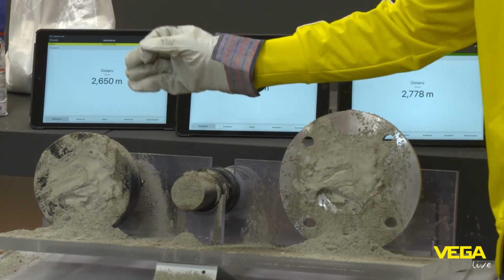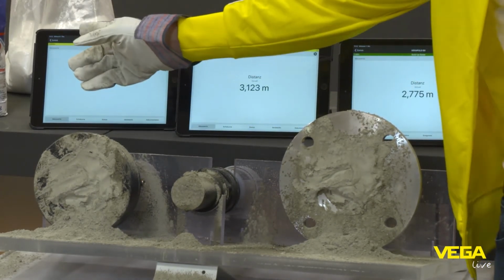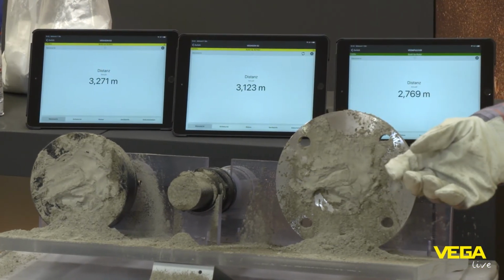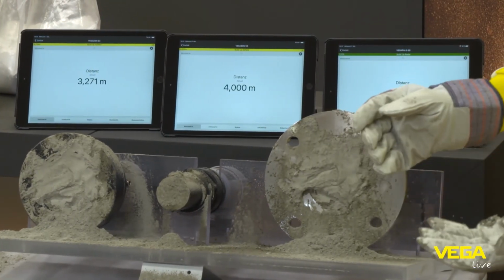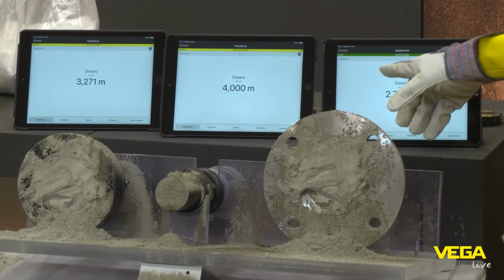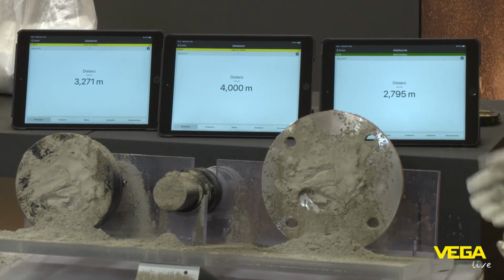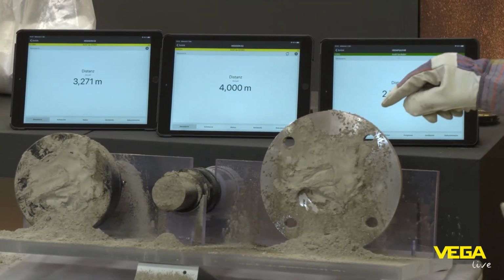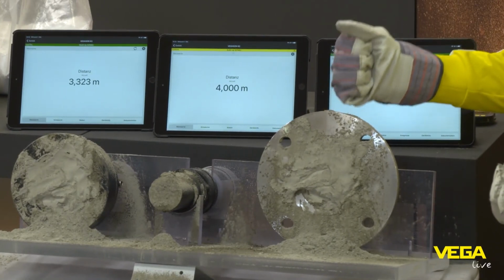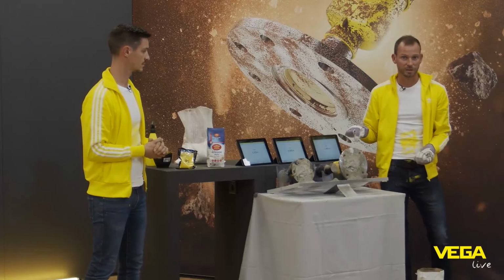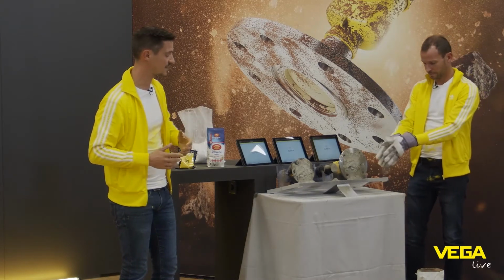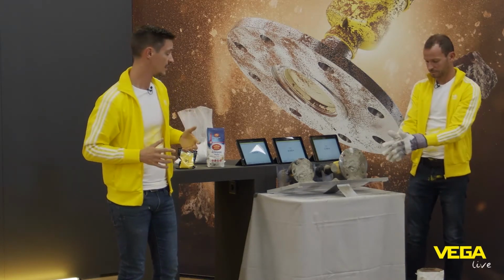And now also our Vegason 63 with the 3-inch ultrasonic transducer is getting yellow, is getting 3.2 meters. So this one is also failing. Have a look at radar. Our Vegapuls 69 is still measuring 2.79 meters, so it's 2.8 meters, even with this heavy build-up. So from all of these three sensors, only radar, only the Vegapuls 69 can live with this amount of build-up. And what is the reason for that? Ultrasonic devices cannot handle these heavy build-ups.